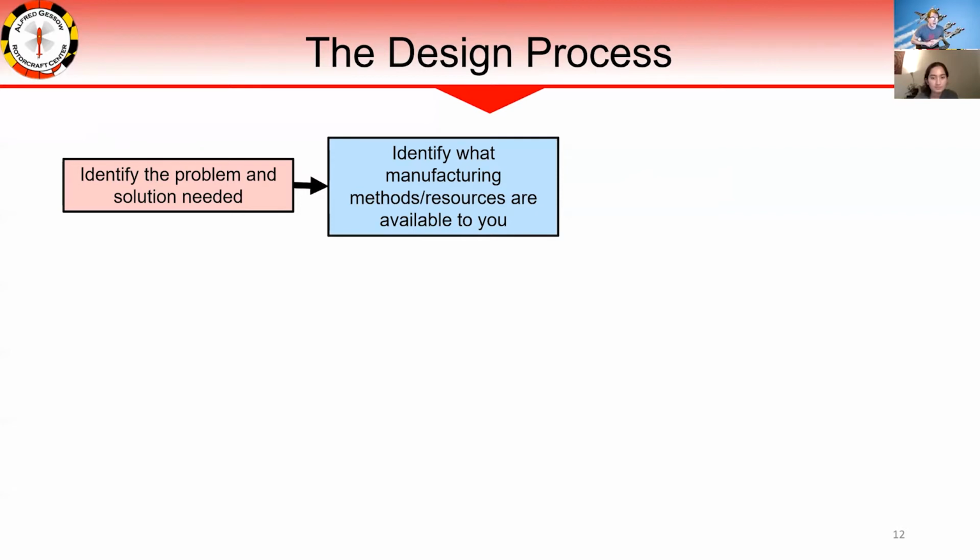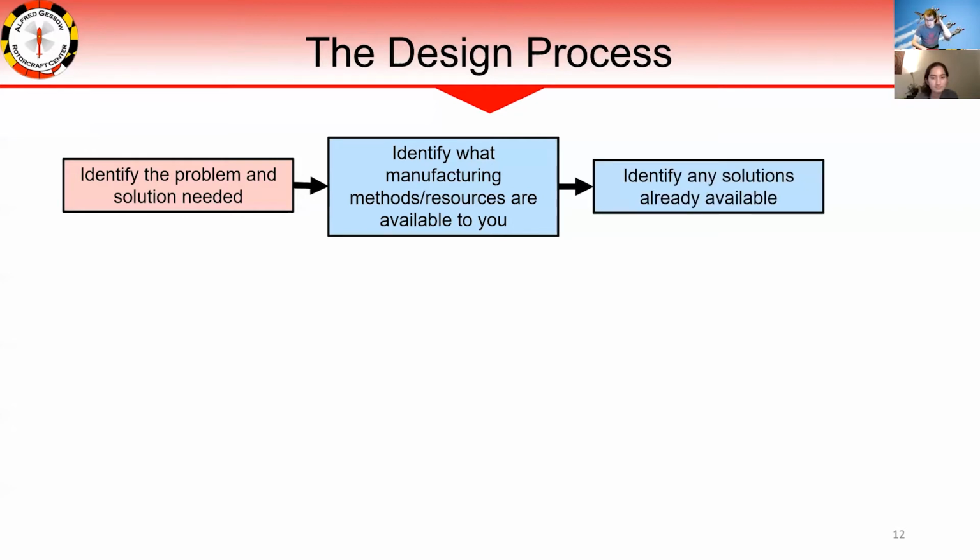If you need a part machined out of steel or aluminum, you better make sure that you either have a CNC router and someone that knows how to use it, or you're able to outsource that work. Oftentimes I see people designing parts that are impossible to manufacture, and you have to make sure it's reasonable. That goes all the way back to the very beginning of when you start CADing. This has to be in your mind when you're making your design.